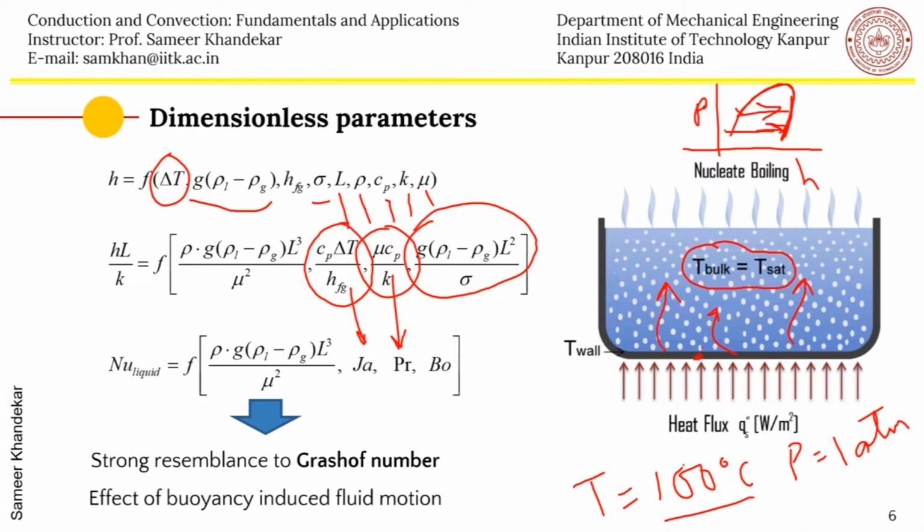When the Bond number is high, the buoyancy is dominant, and when it is low, it is a surface tension dominant system. And then you also see another interesting non-dimensional number, which is the buoyant force divided by the viscous forces, which strongly resembles the Grashof number which you have studied in the lecture on natural convection.